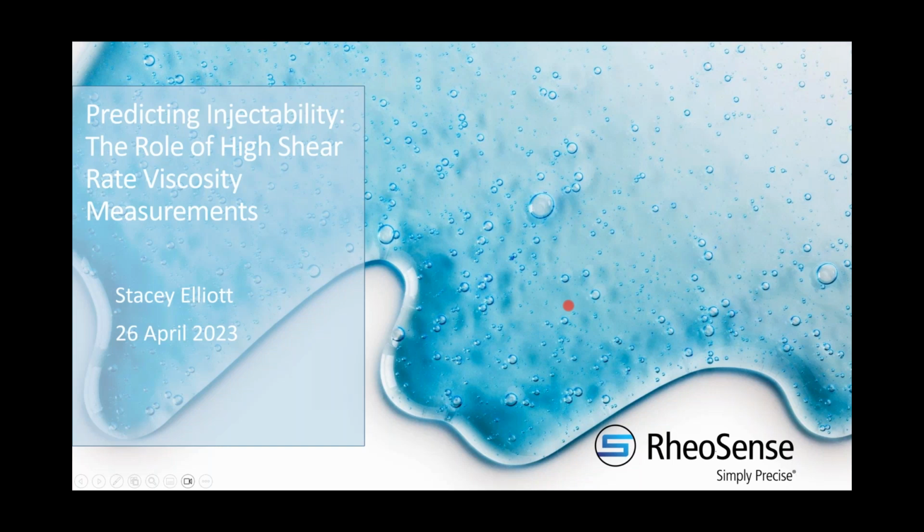That's going to depend on the flow rate, which we're controlling, and then also the width and depth of the channel, which is fixed and well-defined. And then we can calculate stress from that pressure drop across the length of the channel, again in combination with the geometry of the channel. And from these two, we then calculate the steady shear viscosity, which is defined as the shear stress over the shear rate. So this is what we mean in this conversation today. When I say viscosity, I'm talking about steady shear viscosity. And this is how RheoSense, our technology, obtains this viscosity value. And when I share data later that I've collected, it was using this technology.